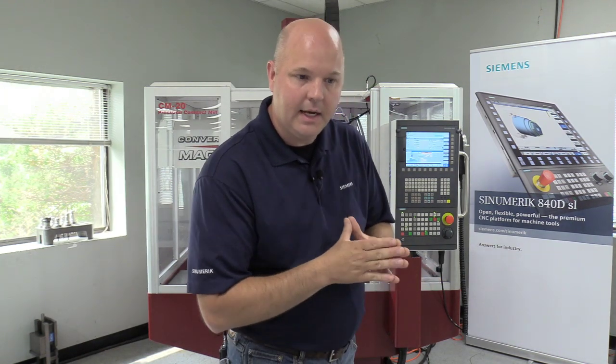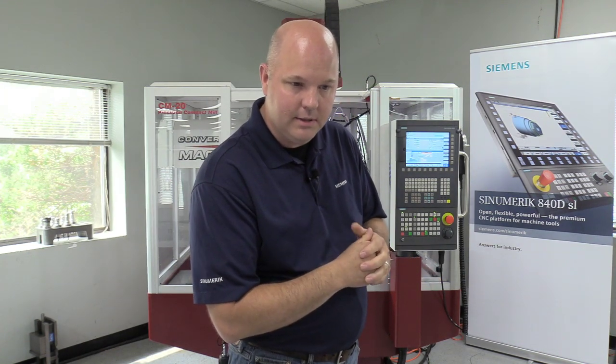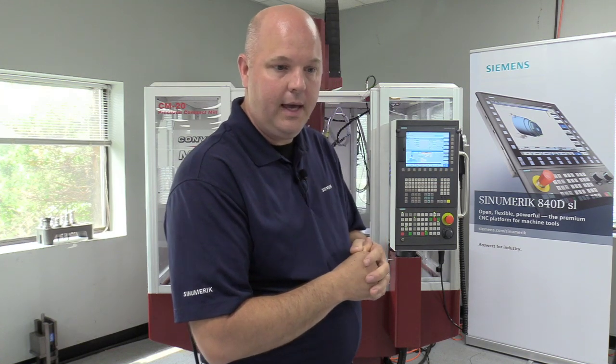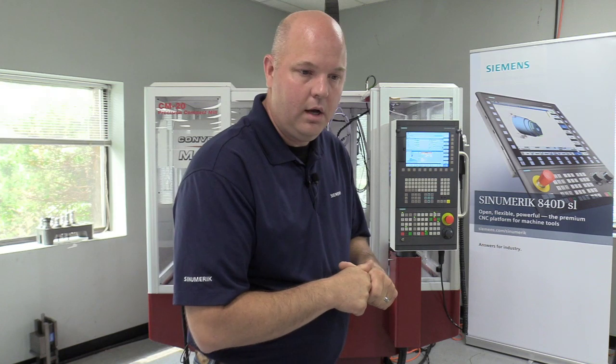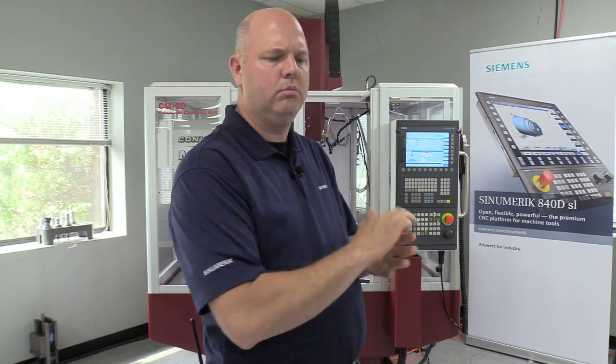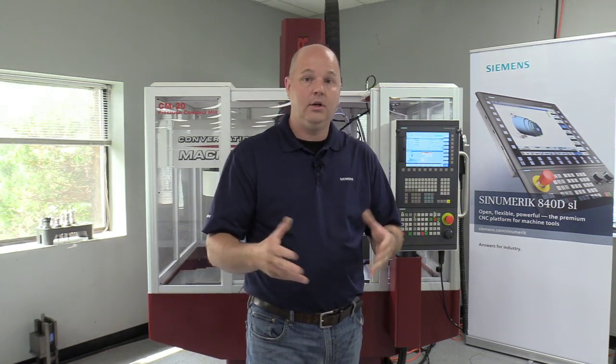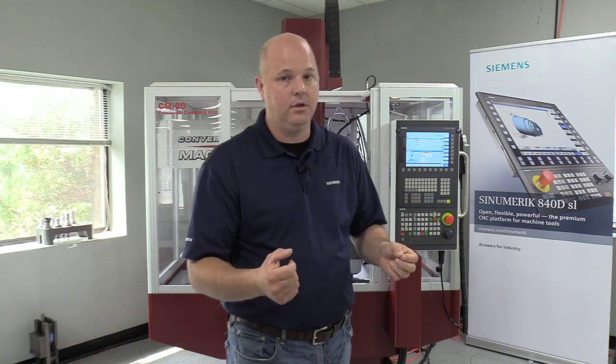I'm going to take a look. We got a couple questions and comments here. What's the advantage to do this instead of tramming a single plate? So I'm assuming they're talking about tipping the part up on some kind of trammed plate like a sine bar or whatnot. The beauty of this setup right here is I can adjust it to any orientation, and I could adjust it mid-program if I needed to.